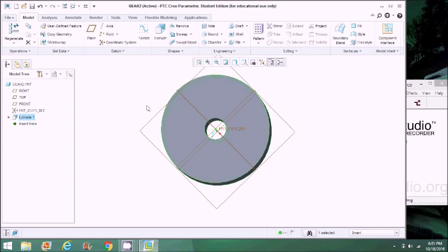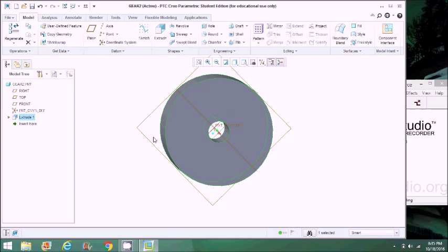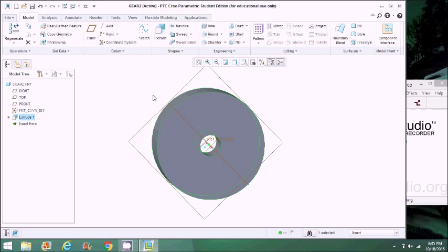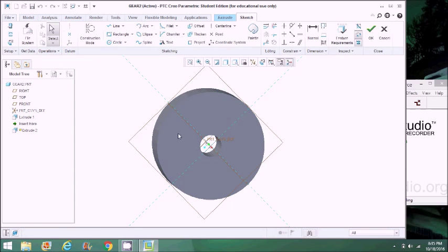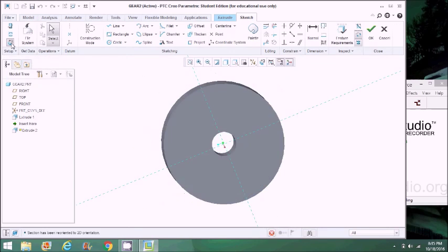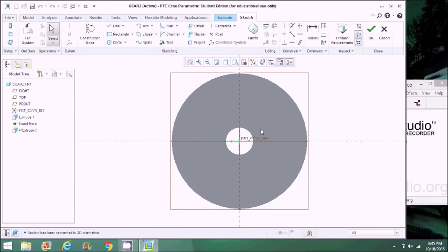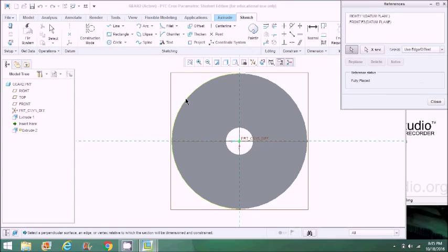Again, if you're looking at the written instructions as well, we're now on step 17, making the teeth of our gear. So you're going to extrude again. Now it asks where you want to extrude this off of, and we want to extrude off of this front face of your cylinder. If you click that, the green shaded region, you then want to click the sketch view button again, and again it brings you to this 2D object. This is your references button, right above the sketch view button. If you click that, you can then reference the outside of your circle.